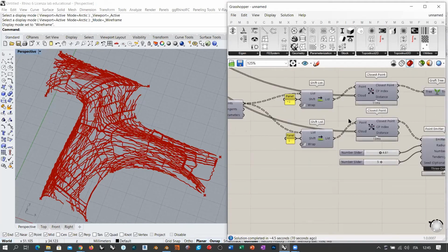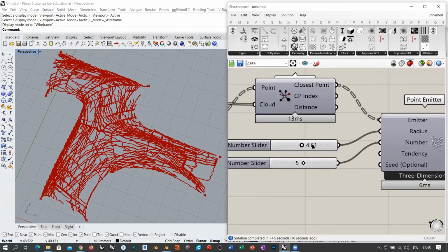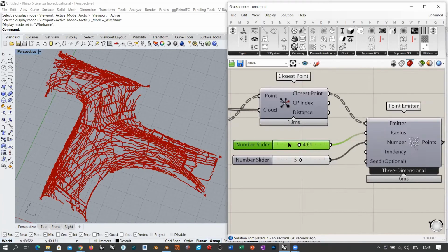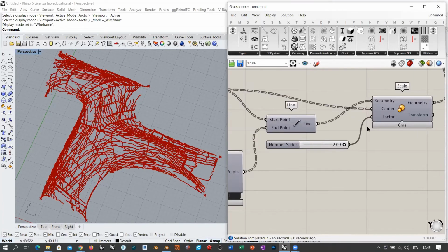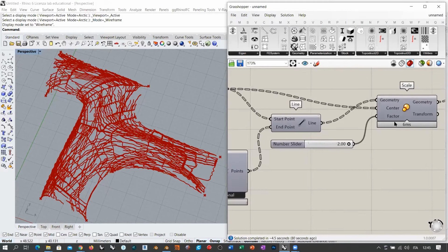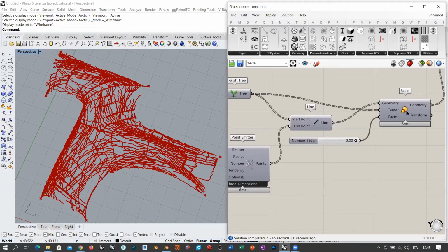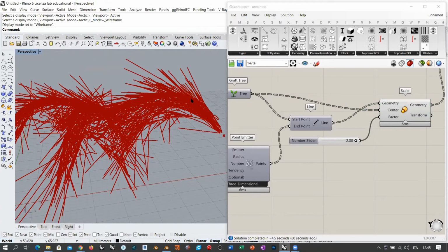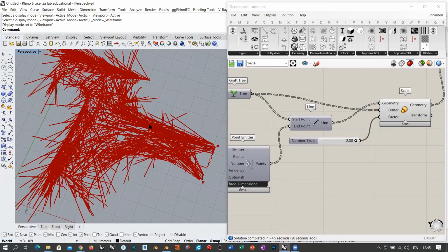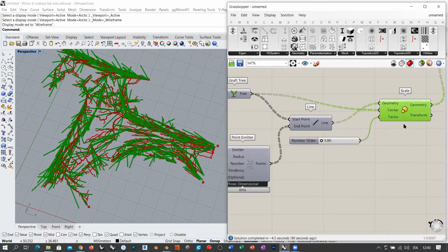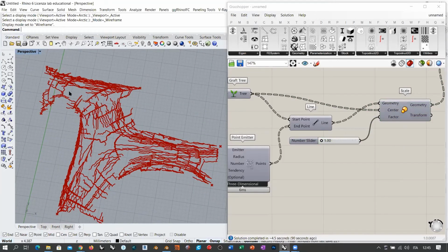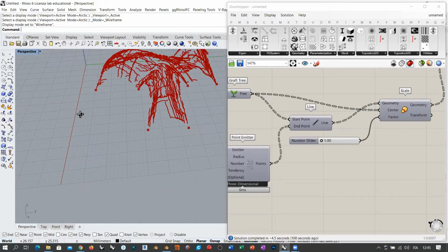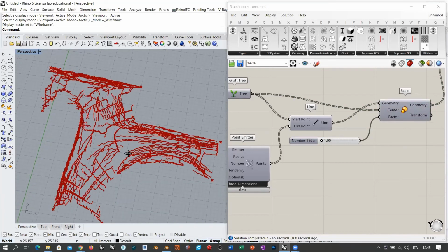Well, actually, the distance depends mainly on the radius that we give to this point cloud, and also on the scale factor of this scaling that we gave to the hairs. Okay, so our scaled lines reach distances which are very far from the actual stress lines. So first of all, let's not scale these. So let's reduce their length. So now you see that we are avoiding filling all the regions with fibers. Okay, so fibers are more concentrated along the stress line.